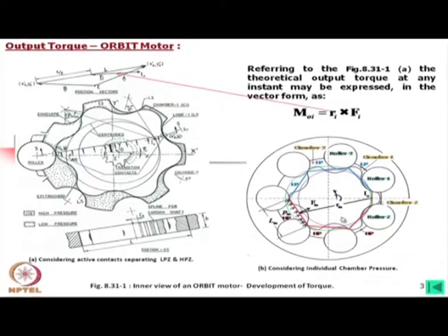Also we consider chamber 1, which is in between rollers 1 and 2, chamber 2 which is between 2 and 3, etc. So, the chamber at the 0th position must be chamber 7 or the jth chamber, which in this case is the 7th chamber. Obviously, the instantaneous point of rotation of the equivalent drum is now situated on the x axis.